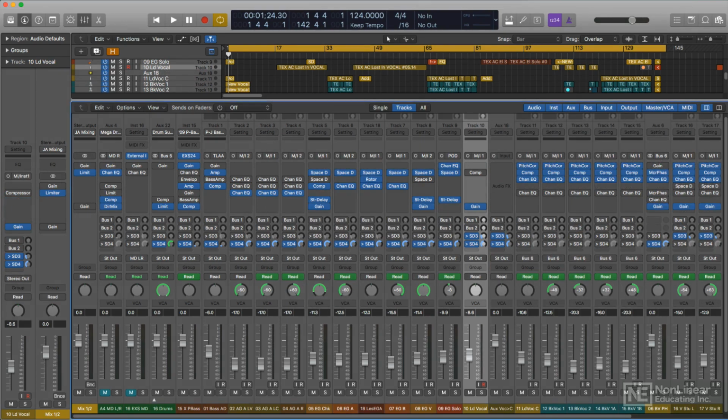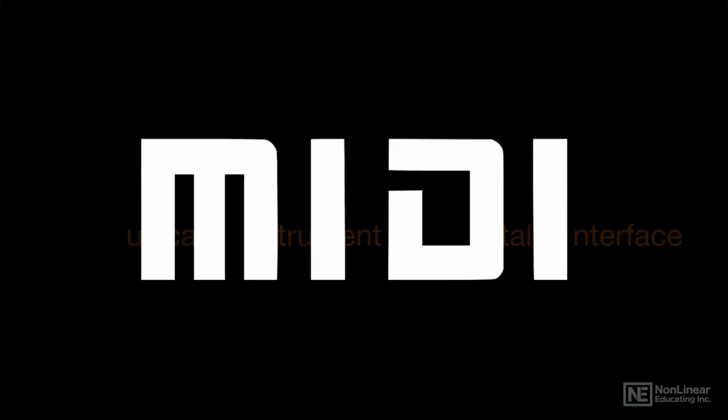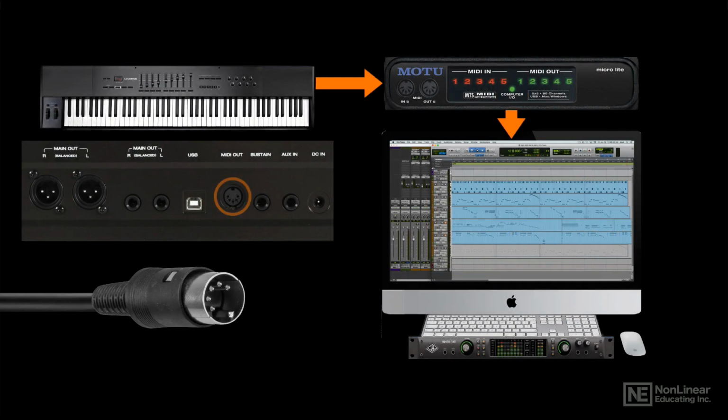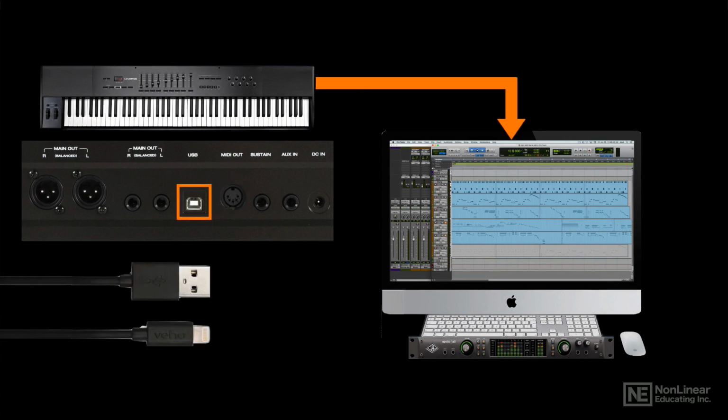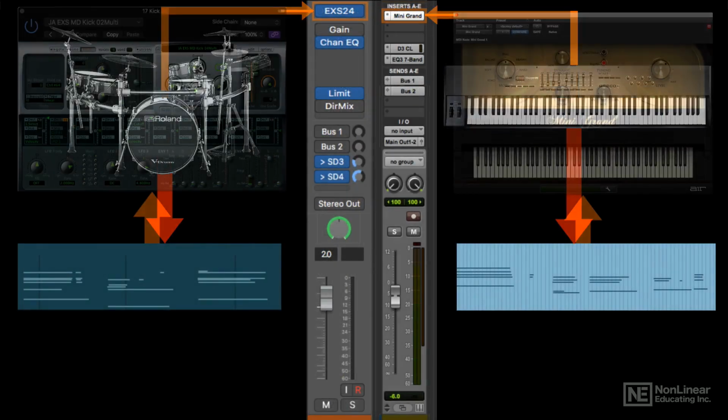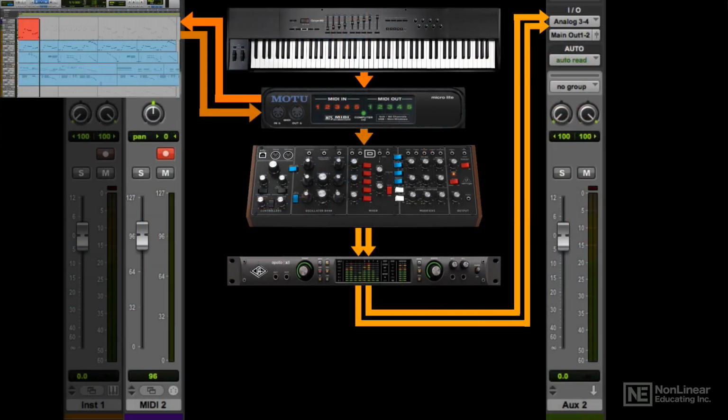And finally, the course will take a quick look at the other type of signal flow in the modern studio, the MIDI signals that control the virtual instruments that are so integrated into modern studio production. It'll include standard MIDI connections, both traditional and modern, and the MIDI and audio signal routing and hookup for working with both internal virtual instruments and external hardware instruments.